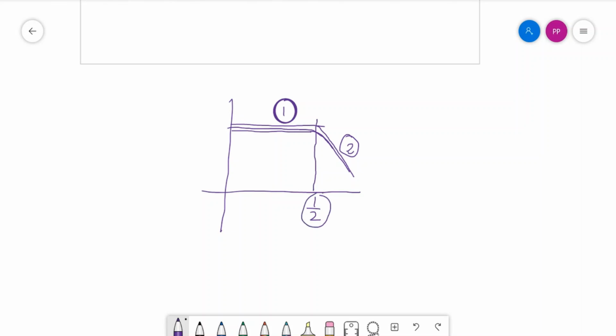The magnitude of the voltage or gain associated with the system will be 1 by root 2, so an error of 3 decibels will be recorded. Such a frequency determines the corner frequency as well as the bandwidth of the system. The system is said to have a bandwidth from very low frequency up to the half power frequency. This is the half power frequency.